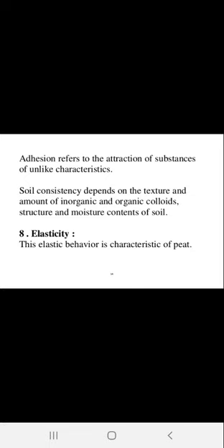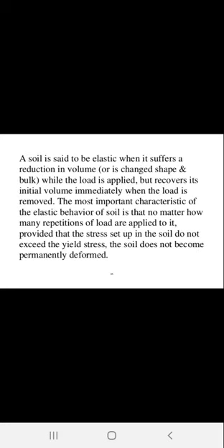The next one is elasticity. As you know from the word elasticity, whenever we have a small change in volume in the soil, it regains its shape within a short time period. That behavior of the soil is called elasticity, right? A soil is said to be elastic when it suffers a reduction in volume while the load is applied, but recovers its initial volume immediately when the load is removed.